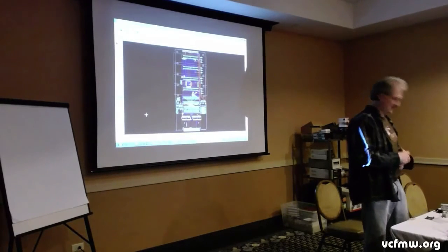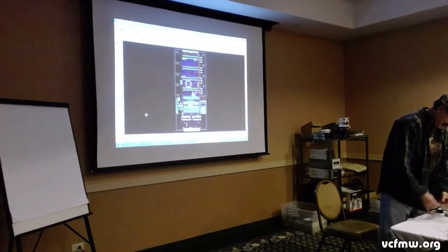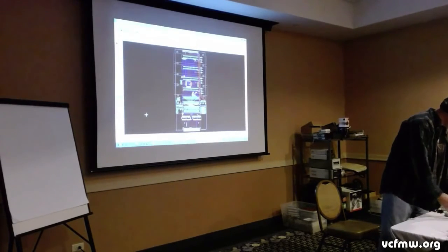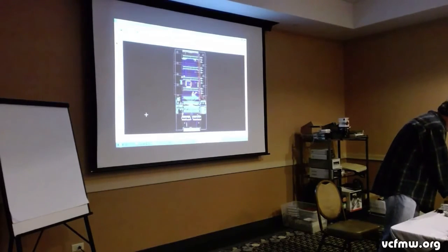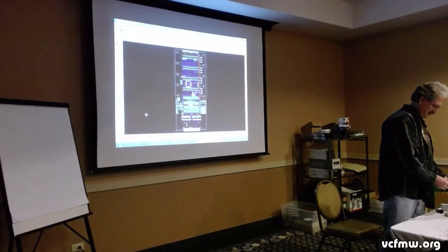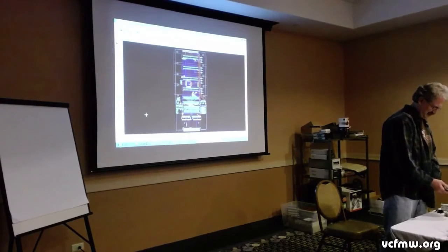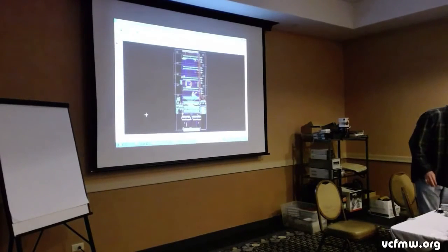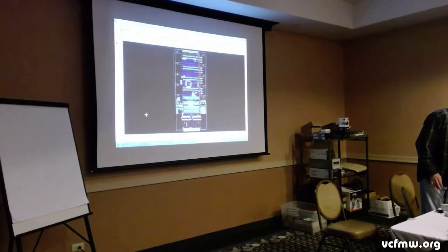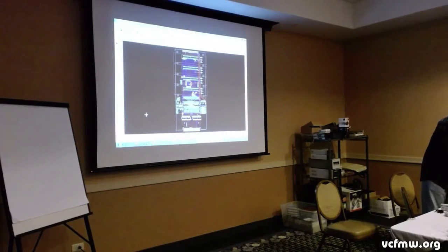Another useful trick on the Xilinx card, I used one in a Atari cartridge, is that these Xilinx cards have bus keeper circuits on their I/O. So if the pin is high, it will hold the pin high, and if the pin is low, it will hold it low. And a nice trick with that is that if you are ever trying to interface with something where you don't have read-write signals, but you know whether something's being read or written, then the bus keeper circuits can allow you to make it so that